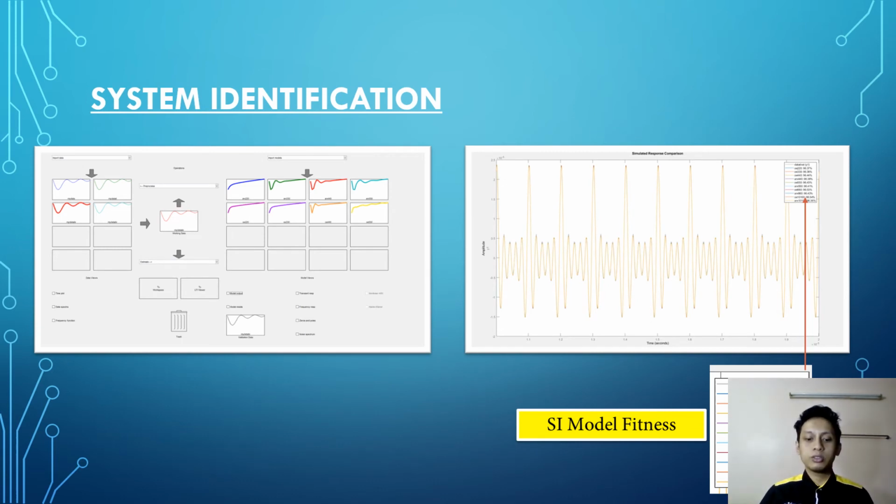Data is then transferred to MATLAB to undergo system identification and neural network. System identification estimates the system model, transfer function, coefficients of a given waveform based on the structure and the number of coefficients the user wants. The estimated transfer function is compared with the actual waveform by using best fit percentage to determine the best structure or number of coefficients to use.